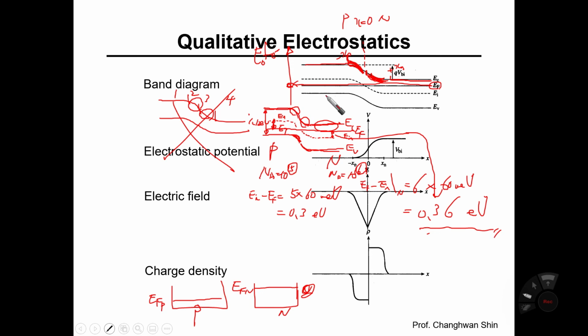But the thing that looks very different from the MS diode electrostatic analysis is this: since both sides are semiconductor material, band bending can be found, observed and drawn on both sides. So I guess this would be a very good question for your final big assignments.